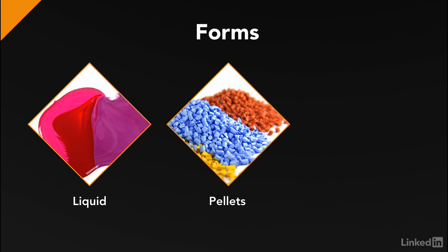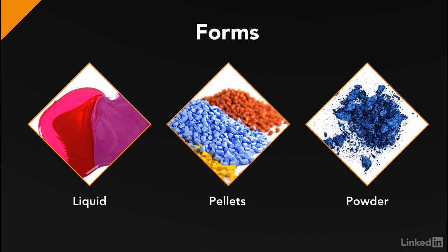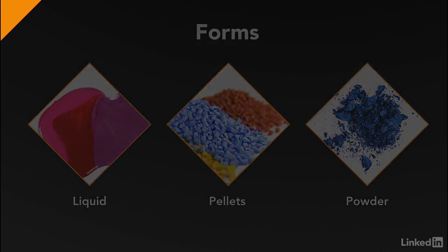Powders are finely ground plastics, generally thermoplastics, used in hot mold melting processes like rotational molding. Because powders have an extremely high surface area, this enables them to melt extremely quickly and flow into all of the surface details of the mold.